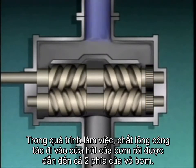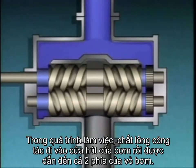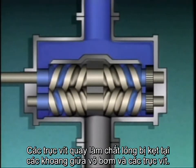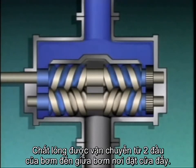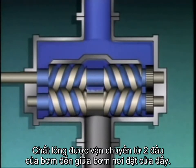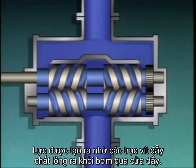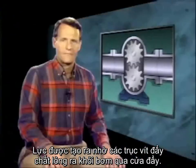During operation, processed liquid enters the suction of the pump and is directed toward both ends of the casing. As the screws rotate, the liquid becomes trapped between the casing and the screws. The liquid is moved from both ends of the pump toward the center, which is also the discharge of the pump. The force that's exerted by the screws pushes the liquid out of the pump and through the discharge piping.